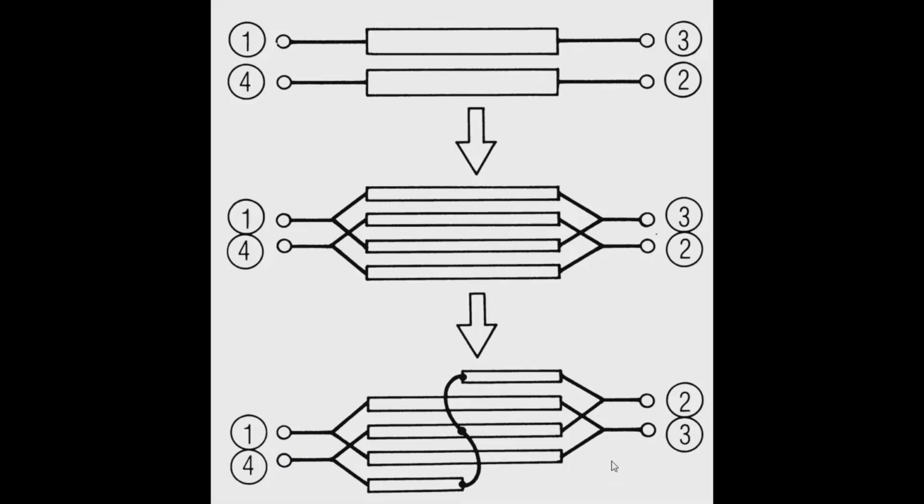That turns out to be a very practical thing to do. Of course, you now have the parasitics associated with the bond wires, not just in the center here, but at the edges. And those will limit the performance to a greater or lesser degree. But it turns out when you actually try to realize one of these couplers, these strips become very narrow.